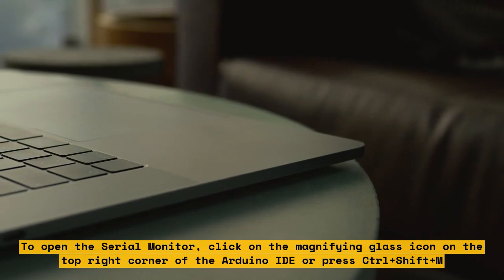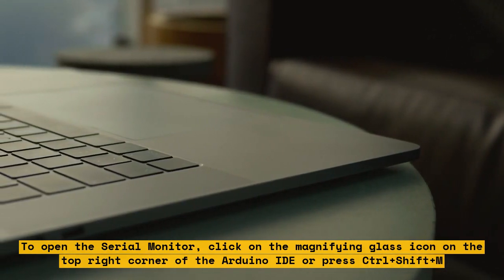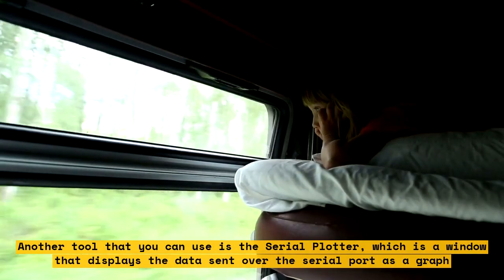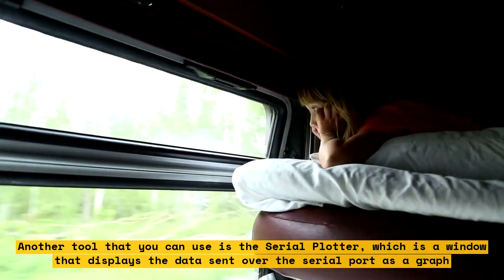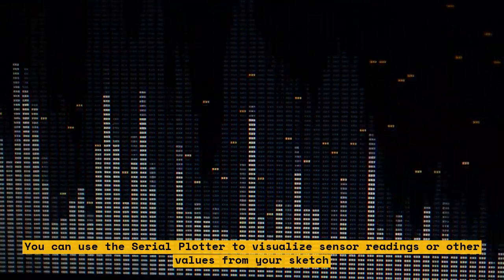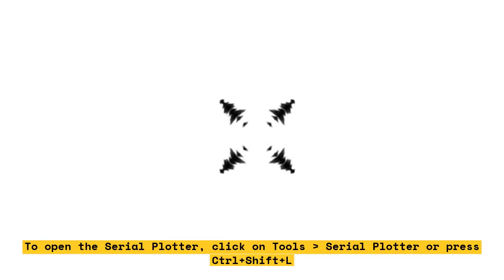or press Ctrl+Shift+M. Another tool that you can use is the serial plotter, which is a window that displays the data sent over the serial port as a graph. You can use the serial plotter to visualize sensor readings or other values from your sketch. To open the serial plotter, click on Tools, Serial Plotter or press Ctrl+Shift+L.